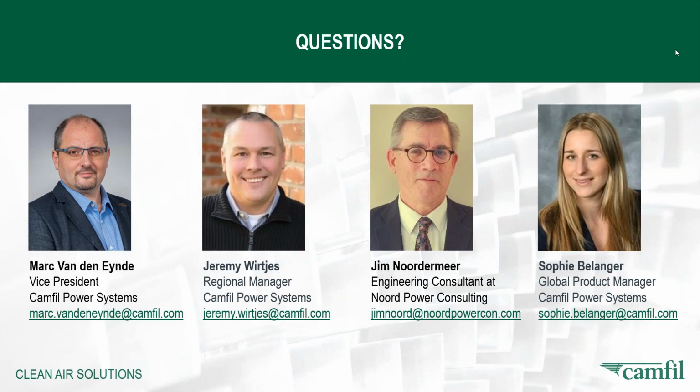The other way, of course, is trying to use an E10 filter which has a higher dust holding capacity. So instead of a 330 millimeter depth one, go to a deeper one like our 3D600, for example, without having to change the pre-filtration. But again, this is the kind of thing that we can assess and simulate within our LCC powered analysis to show them really what would be the most beneficial. And we have seen in real life that we have moved in some cases even from 3-stage systems to 2-stage systems without needing to shorten life on any of the stages, actually extending the life on both stages.